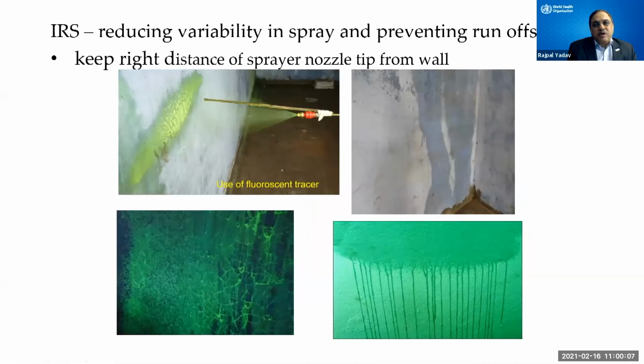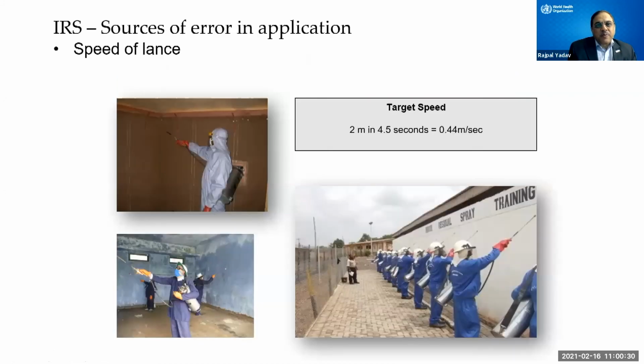And when you attach a control flow valve, the spray is much more uniform. So for example, this is the uniform spray. But when you don't use one, it can be draining on the wall, or you can see that a lot of liquid is flowing down, and this is not a good idea. And therefore, uniform spray requires that we attach a constant or control flow valve.